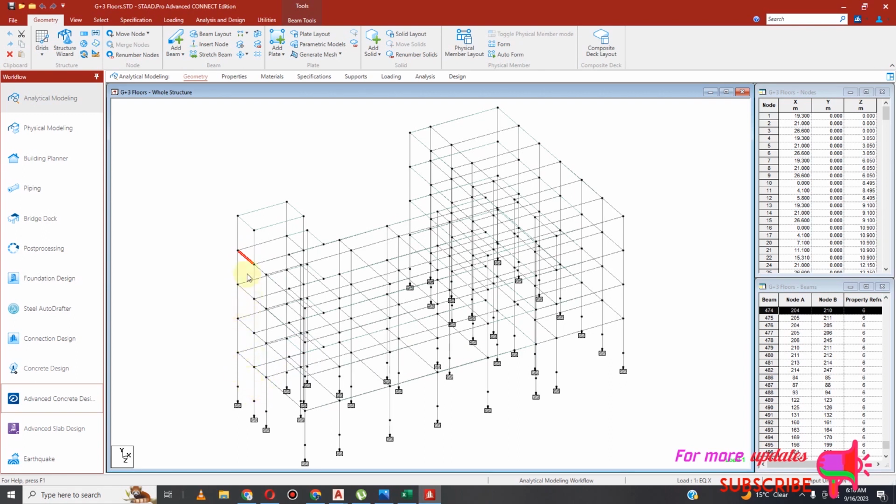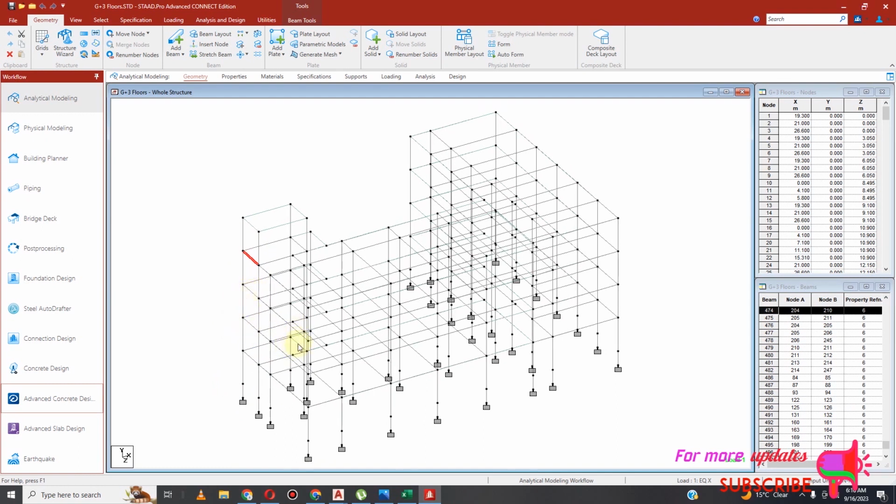And also the beam, the span is not that big, so I think 450 by 200 should be okay, because the span is not that long, so it can hold that staircase landing, and also landing 1 and landing 2 without issue, so that should be no problem. And also for the column, we use 400 by 200, actually 225, so that cross section is already bigger than the rest in the structure, and so it will pass.